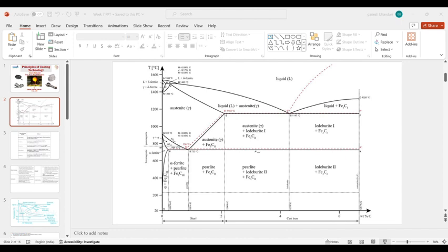Before the tempering process, one process comes which we call the quenching process. Okay. So in quenching process, what we generally do, we heat our sample beyond upper critical temperature and we cool it down with a very fast cooling rate.